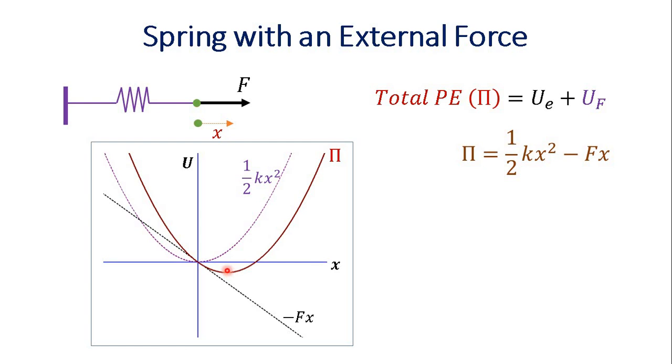So now our concern is how to denote this minimum potential energy mathematically. Mathematically we denote this point like this: d pi is equal to 0. That is, infinitesimal change in pi, and since pi is a dependent variable which depends on x, the change in pi that is brought by infinitesimal change in x is 0 at this extreme point, right?